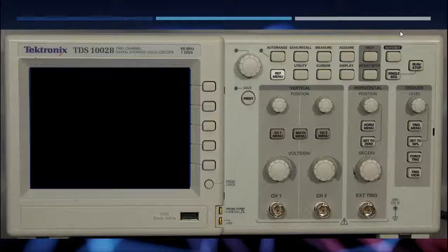Your typical oscilloscope on the front typically tells you 2 sets of important pieces of information. First, if you look up on my oscilloscope, you'll notice that it says that this oscilloscope has 2 channels and also that it is a 60 megahertz scope. What that simply means is that the oscilloscope allows me to put 2 signals into the oscilloscope, into channel 1 and channel 2, and also that the maximum frequency any of those signals can have is 60 megahertz.